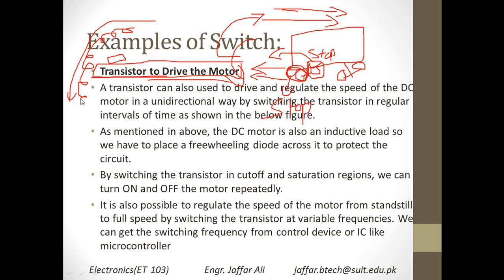The IC that is basically used in certain applications or robots is the L293D. This is the driver IC, and you will be using this in the coming semesters if you are making some kind of mini projects. Such a scenario occurs when you want to control a motor or a robot car or any car. You will need this motor driver IC, and you can control it using a transistor as a switch.